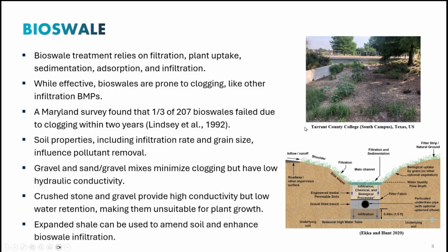In different parts of the US and the world, we have seen the effectiveness of bioswales, but the major problem with them is clogging. After a few years, when the surface is clogged by the sediment captured in the bioswale, their efficiency would reduce. There have been some studies in Maryland saying that out of 27 bioswales they installed, one third of them failed because of clogging, meaning that in a few years you have to go and scrape the surface or replace the medium to increase their efficiency.